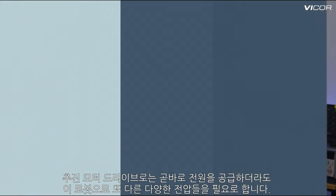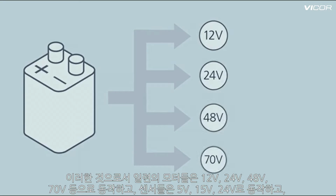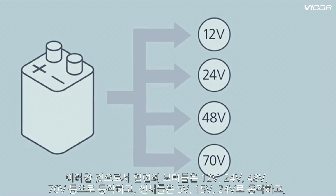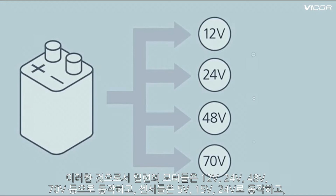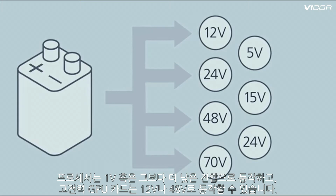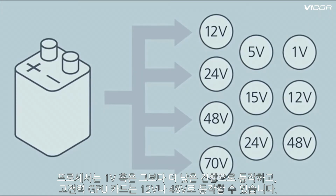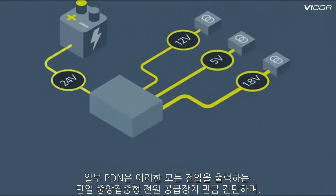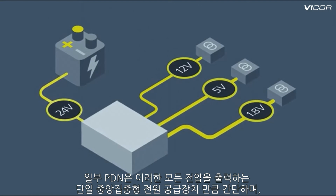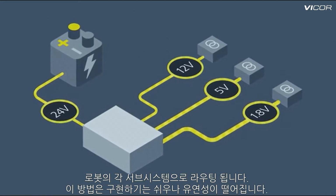But there are other voltages needed within the robot that are different. These motors may operate at 12, 24, 48, or even 70 volts or higher. Sensors can be at 5, 15, or 24 volts. And the processors can run at voltages that are 1 volt or lower, and you can even have a GPU card in there running off of 12 or 48. Now, some PDNs are as simple as a single central power supply that puts out all these voltages, which are then routed to each subsystem in the robot.